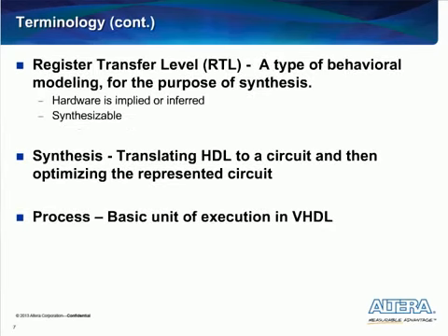The term RTL, or Register Transfer Level, refers to a type of behavioral modeling. With RTL, the design is described in terms of register stages with combinatorial blocks of logic between them. Synthesis is the act of translating this text-based HDL into a circuit and then optimizing that circuit. And the process is the basic unit of execution in VHDL.